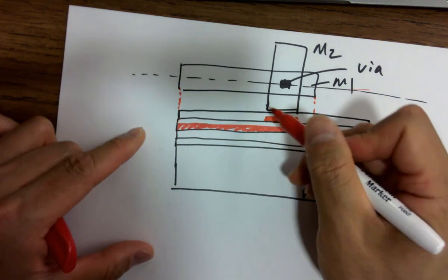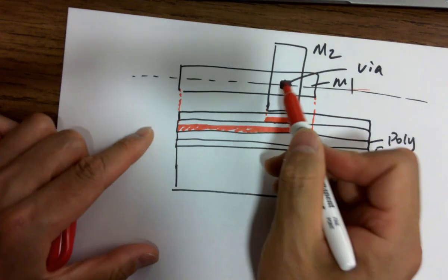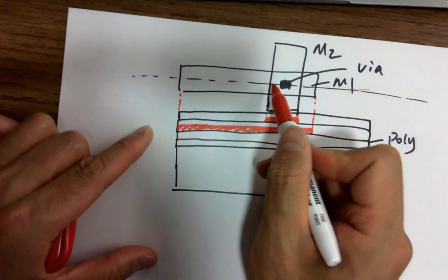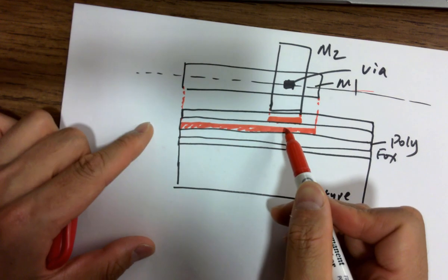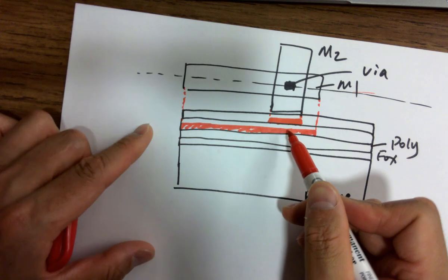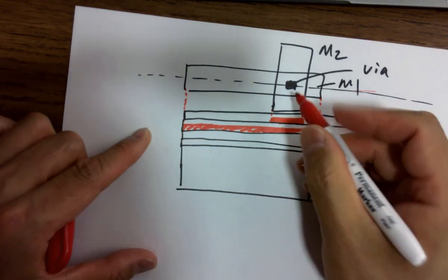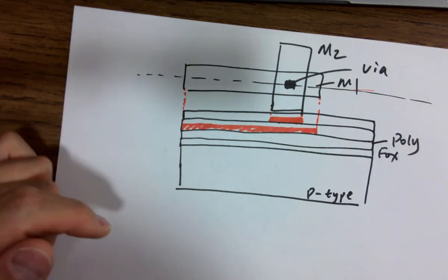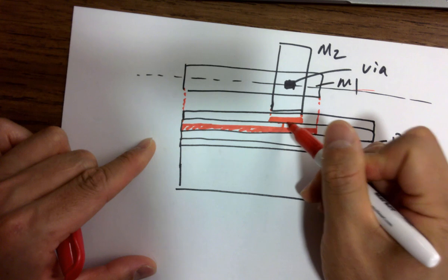Okay? Only this wide. And because this dashed line crosses this via, you'll see a via here as well. If it doesn't cross this via, you shouldn't have a via, keep in mind. It crosses the via, so flip it, looking from the side, you're going to see a via. That via is making a connection between metal 1 and metal 2, so definitely it should make a connection.